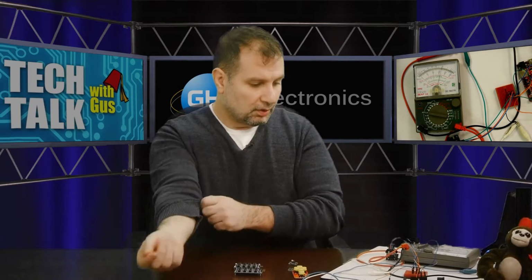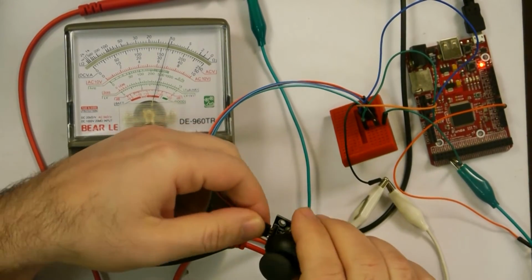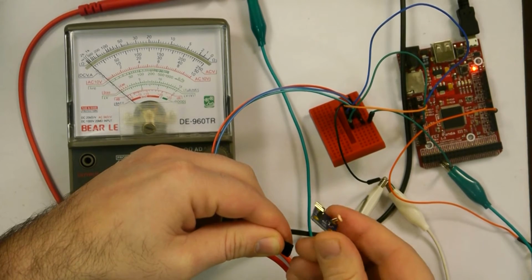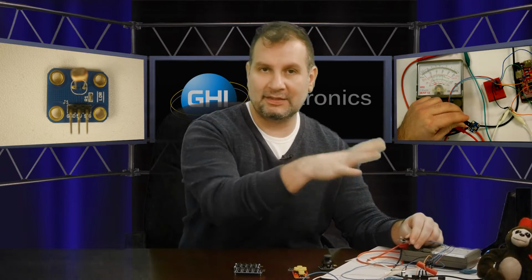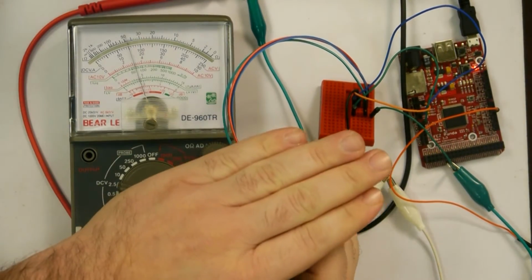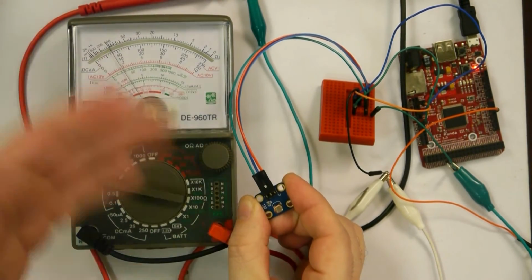Nice. Now, I want to show you an example of a sensor. In this case, you just have a variable resistor, but I want to show you a typical sensor. This, for example, is a light sensor, which is basically a resistor that changes value depending on how much light it's getting. So let's try it. Darker, brighter. And you can see the output changing on the voltmeter.